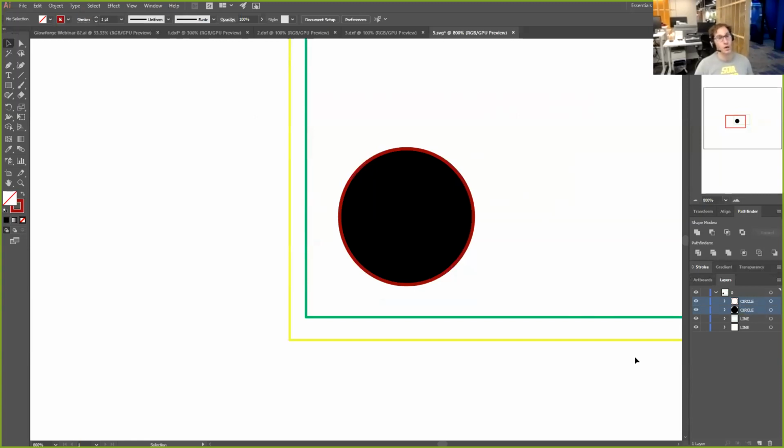Oh, nice. Now, I would love if Glowforge is listening to work on that for us so that I can pick a fill and a stroke in one object, bring it over to the Glowforge, and it'll automatically discern that I want to do two things to it. You know, maybe an engrave/raster and a score. I would love it if you guys would do that. But in the meantime, I hope everyone realizes that you have to duplicate your object and make one a score and one a fill, or both fills of different colors, or both strokes of different colors, and the Glowforge interface will know, as long as the colors are different, that it's two different things.